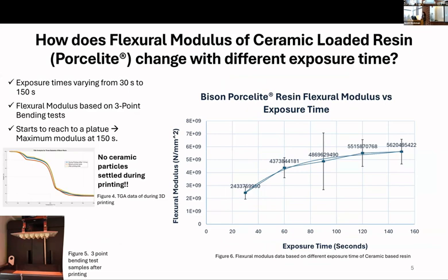So we had to try with an exposure time of at least 30 seconds, because the working curve was based on a single layer, and our normal prints were multiple layers. Our minimum exposure time was 30 seconds, and we went up to around 150 seconds.